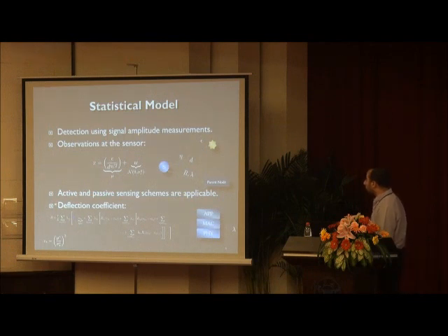Given this observation model, we can get this expression for our detection coefficient. This is our objective function. And these are our design variables. So this is our representative communication rate, where the sensor communicates back to the parent node its observations. Now if we look here, the expression looks complicated, but it's not actually very hard to see that it is simply the signal to noise ratio of each sensor, multiplied by lambda, which is the probability that the information will be successfully transmitted to the decision unit.